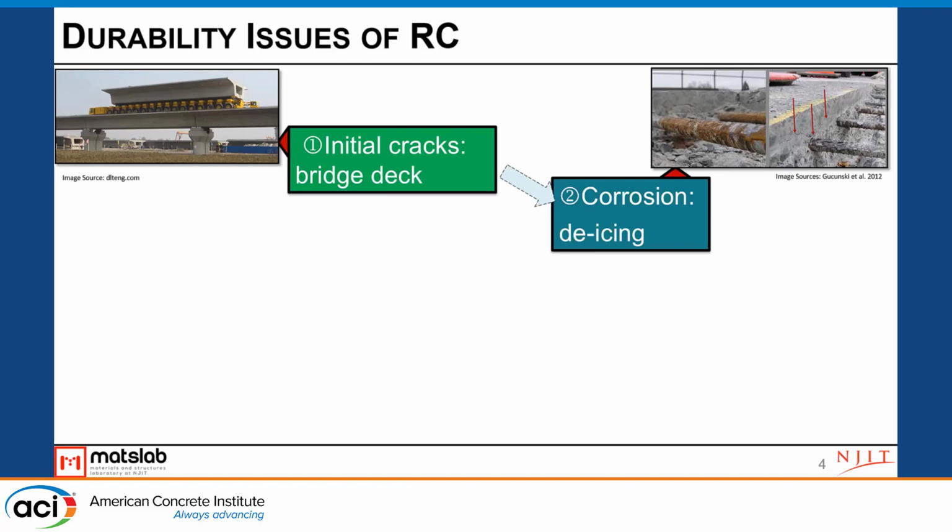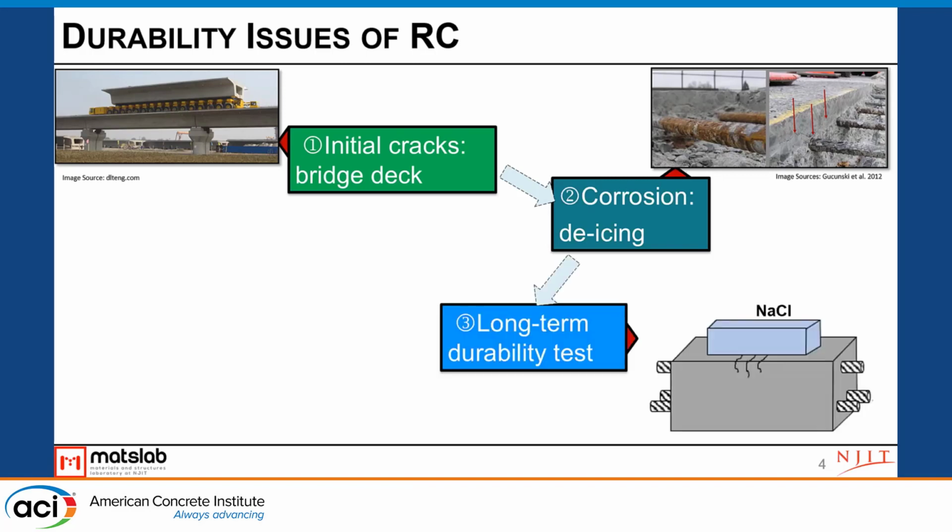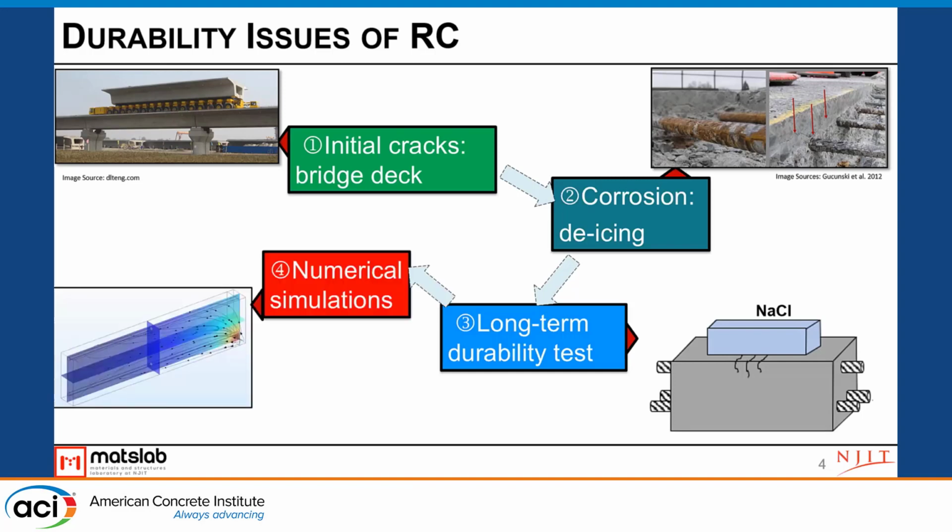So what we want to really figure out here is what's the impact of the crack width, and also how the corrosion behaves differently if we apply different surface chloride concentrations. So one very straightforward method is, of course, to conduct the long-term durability test. And maybe another approach is to use the numerical simulation.